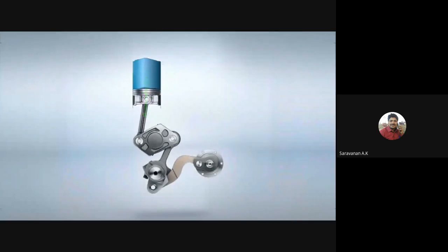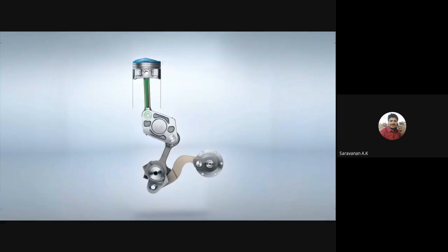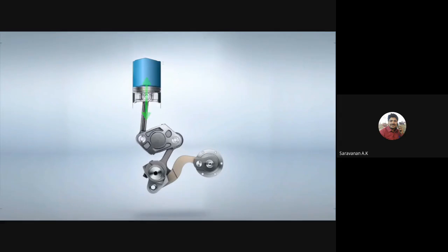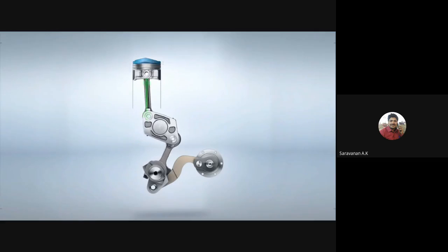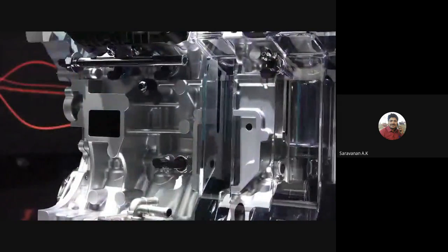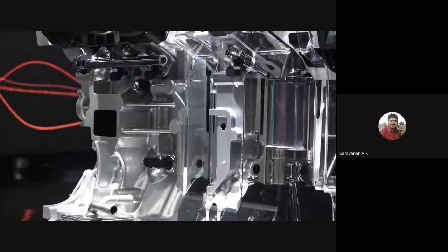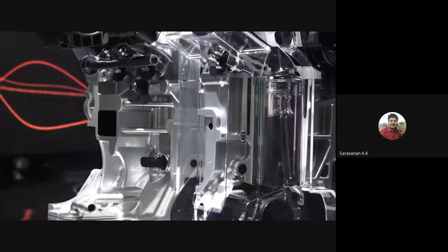This engine, however, maintains a nearly vertical connecting rod for the combustion stroke as the piston is moving downward, which eliminates the side force from combustion against the cylinder wall. With less force against the cylinder wall, there's less friction, and as the force is all in the desired direction, this is more efficient. Now, looking at the cylinder liner, you'll notice it's very shiny and reflective.